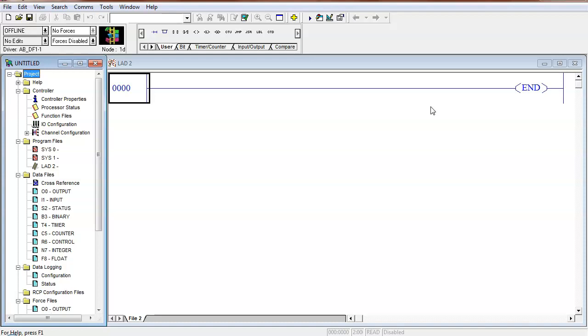So what we're doing is we're writing programs, but we're going to write them in a language called ladder logic. Even though this guy right here has no idea what ladder logic is, it runs machine language, all it knows. But what these tools do is allow us to write high-level language programs in a language that we understand. Then when we send it or download it, it compiles it and automatically converts it into machine language for the PLC. So if you looked inside that memory, all you'd see is ones and zeros.